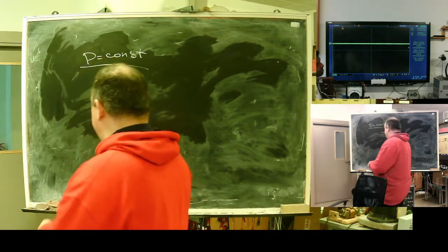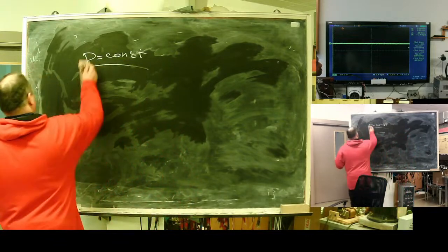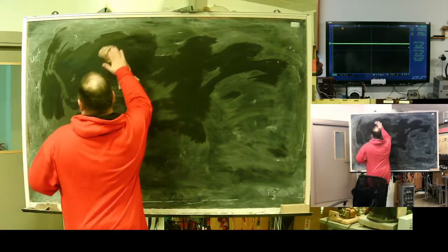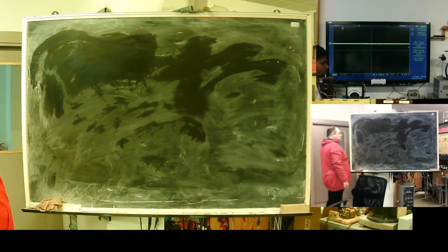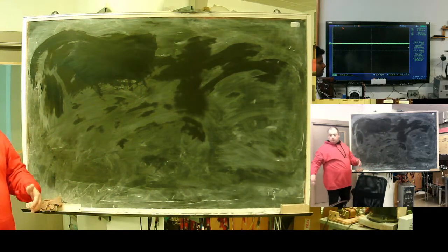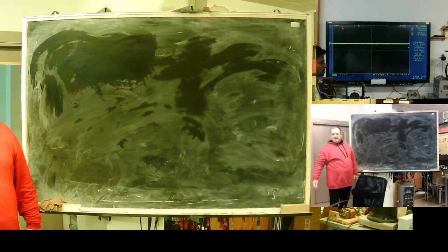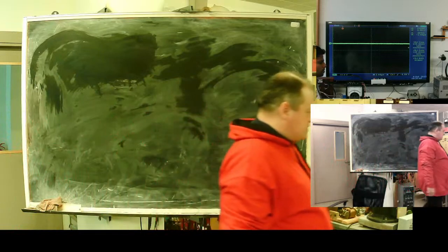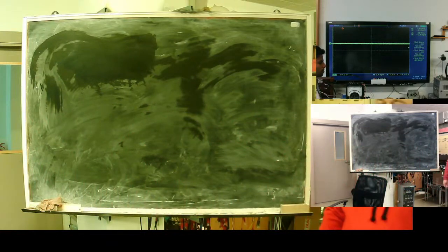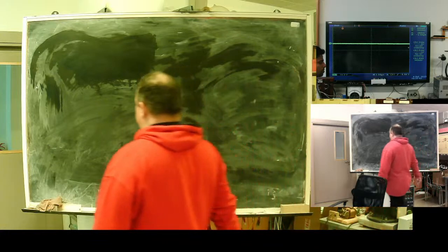This will not work. First, we need to somehow reflect the non-linearity of the law. And one way to do it, an idea, is to reflect this non-linear load as a controlled current source.